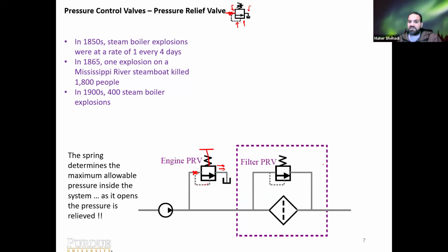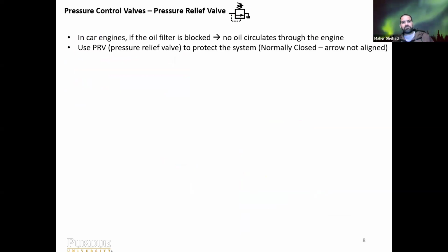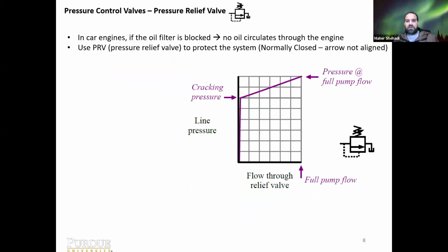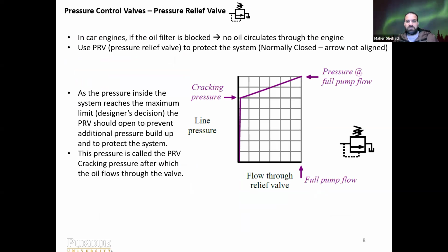It's good to add, for example, a sensor to sense that oil is now passing through this. So it gives you a yellow, red, green. I should color them, but it gives you a yellow alarm that the filter needs to be changed when the oil starts passing through the bypass, so that you would go and change the filter at one point. Okay, so I'll let you read through these.